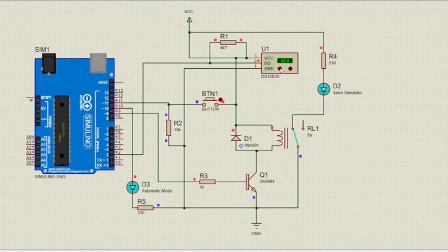By pressing a button you can set a state for the valve at the desired time. In other words, if the push button is pressed while the valve is in one direction, it will remain in that state without checking the temperature until the push button is pressed again. The same will happen if the valve is in the opposite direction.